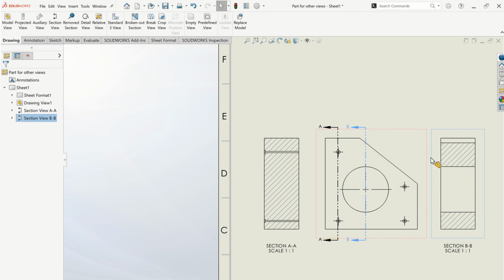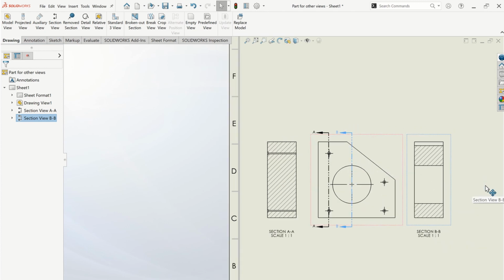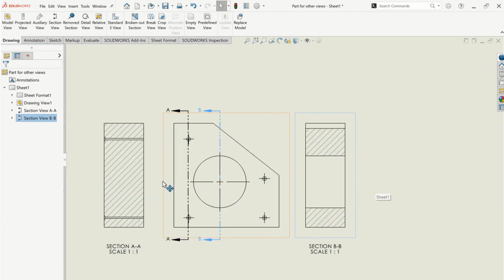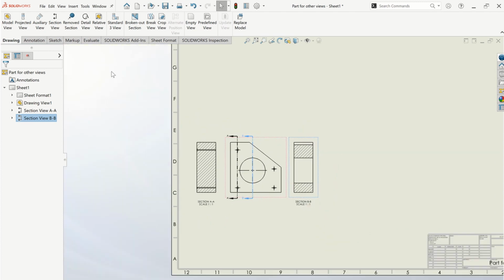This is the part over here, and this one will be non-hatched because it is not cut over here, right? So when it's projected over here, it will become like this. The hatched area is the area that is being cut. Okay, so this is the solid part. So you'll see this will be the sectional view.